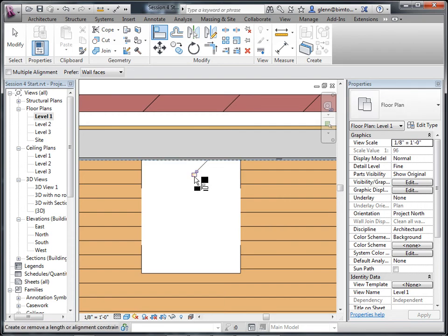Yes? While you're on the topic of tabs, if you're trying to select an object where there are multiple objects layered, do you tab between the objects too? It'll rotate through. All the objects? Yes, it rotates through the whole system, from what it thinks is the most likely to the least likely. So any line within that range? Yeah. It takes some work. Tabbing is an interesting thing about how you get down to what you want, but generally you'll eventually get to it.